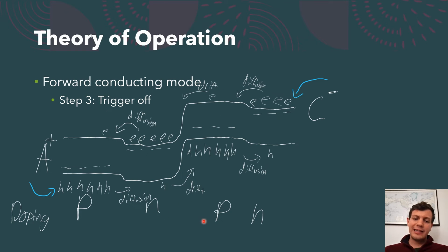Keep in mind that these N and P regions are doped pretty small, so it is possible for these charges to totally drift into this other N region. And that's totally energetically favorable given the low potential of the electrons here. So the electrons want to come down here. They've drifted down here, and then there's a high concentration here, so they're going to diffuse over here,